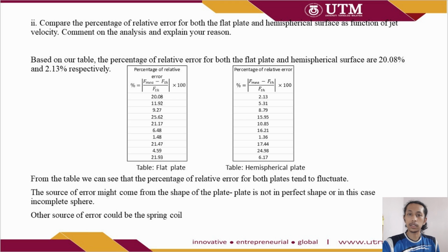The force equation depends on the angle, which is the impact of velocity from the water to the surface of the plate. The other source of error might be the spring coil, where the shape of the spring coil must be straight. If not, then the velocity which is applied by the water is inaccurate.